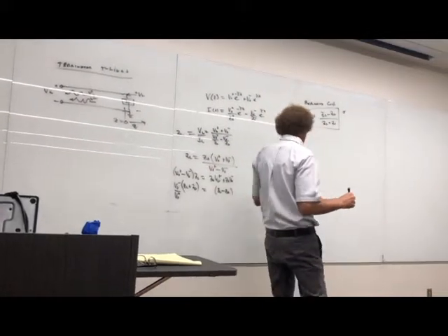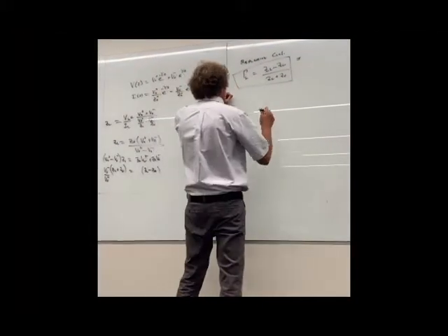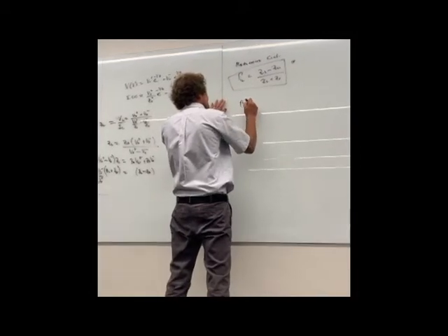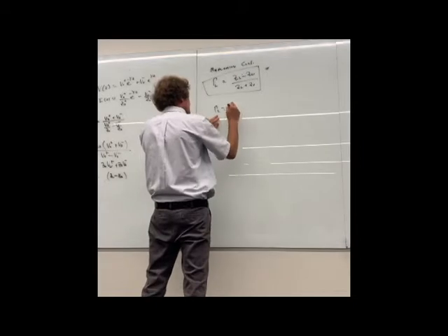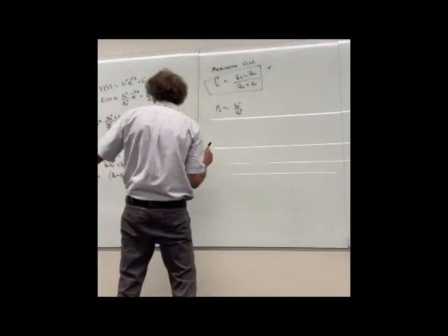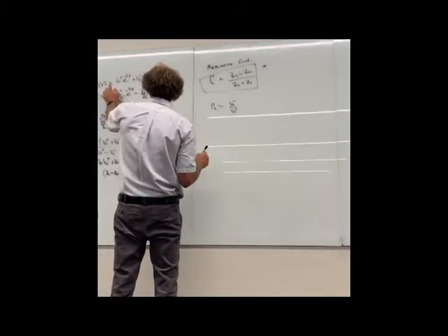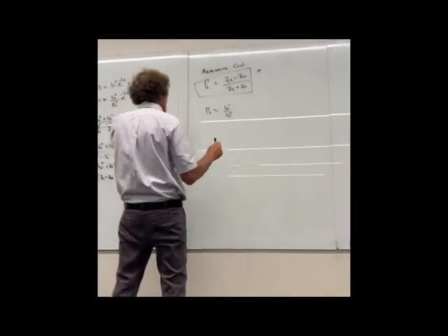So now what we can do is this. We know the reflection coefficient, this is what it's equal to in terms of the load impedance and characteristic impedance, but it's equal to V0 minus over V0 plus. So what's usually done is we rewrite these equations in terms of the reflection coefficient.